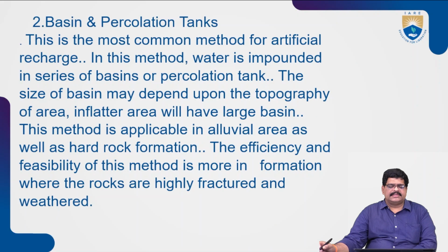Next one is the second basin type, percolation tanks. What are percolation tanks? Percolation tanks are the most common method used for artificial recharge, and water can be impounded in a series of basins or percolation tanks. The size of the basin may vary with the availability of area and storage capacity, and the feasibility depends on the rock formation, which is highly fractured or weathered. So the second method is the basin or percolation tank type.